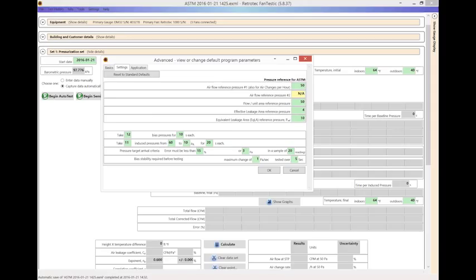So notice that our induced pressure is going to go from 60 down to 10. And what we want to do is make sure we started at a low pressure and went above the 50 Pascal reference that we're after, so we can actually get a range above and below that. If I were to just close this and do the test, it would probably take maybe 10, 15 minutes, depending on the challenges that the fan had to get up to each one of the pressures and speeds.